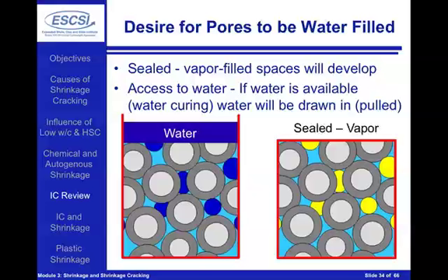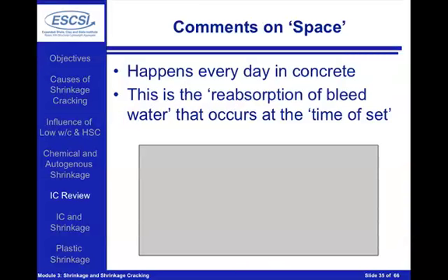So the real difference here is that with external water curing, we're going to draw water in from the outside, but in the sealed case, we're going to have the system undergoing some self-desiccation, where vapor-filled spaces are forming inside of the concrete.